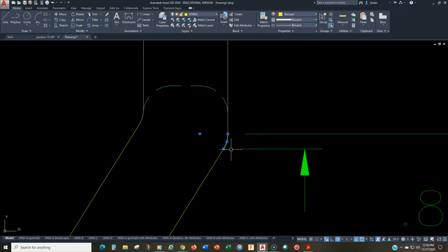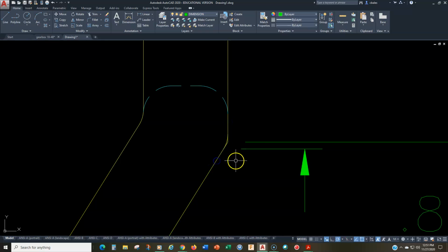All right. So that's why I say don't put the fillets in yet. Put the fillets in after you get the dimension. Okay. So what I'm going to do is I'm going to undo my little fillet there. I'm going to fillet it with a radius of 0. That's a little trick that you can do to undo that, and you get an actual corner in there, right?